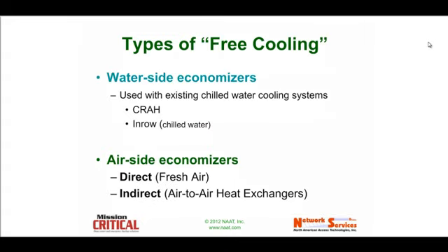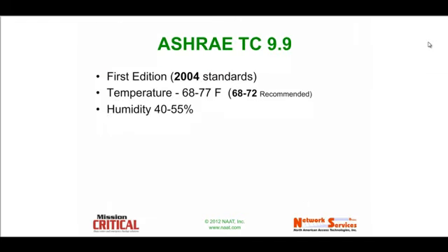And of course, within the water side, Chris will cover that, as I said. Within the air side economizers, there's two basic types: direct, the so-called fresh air cooling, and indirect, which involves isolating the air via an air-to-air heat exchanger. Before we go down that technical path, we really want to take a look at a little bit of where